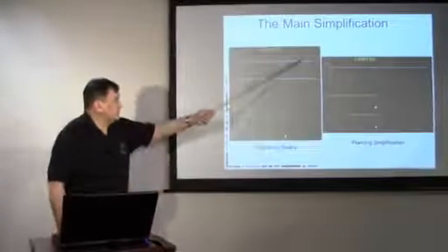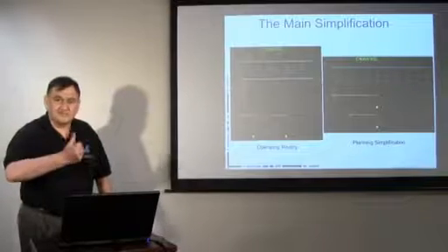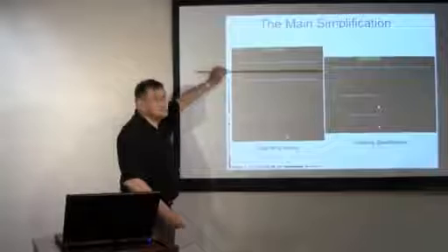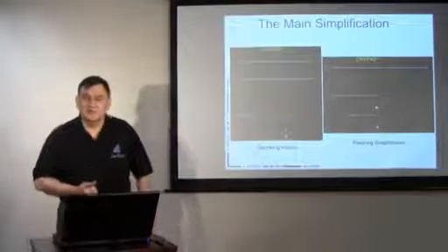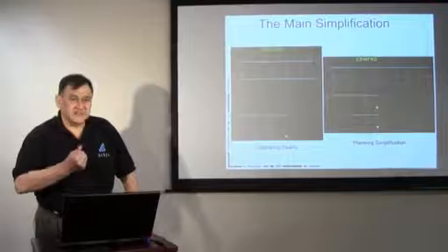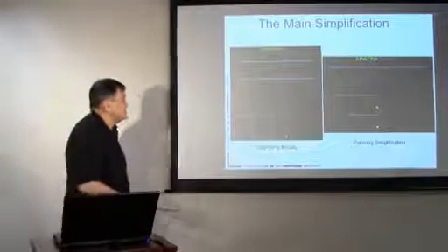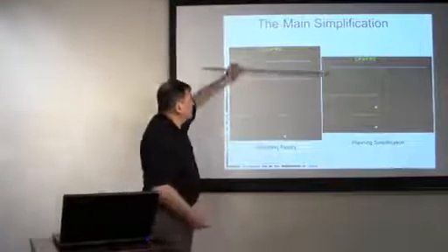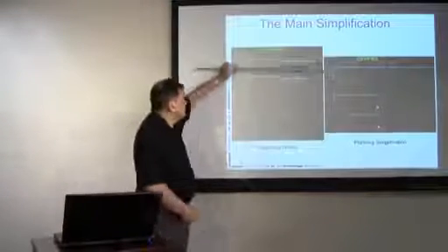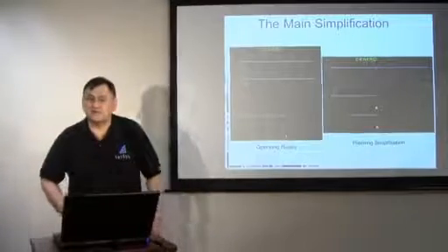A bus is really all the things that are electrically connected. So in the normal configuration, all of these breakers would be closed, and a planning engineer's view is that I really have one electrical bus because everything is at the same voltage. A bus in a planning engineer's view is everything is at the same voltage. If for some reason the bus was to be split, let's say we opened all the middle breakers, then the planning engineer's view is, well, I now have 2 electrical buses, one here and one here, because they're now operating at the same voltage.